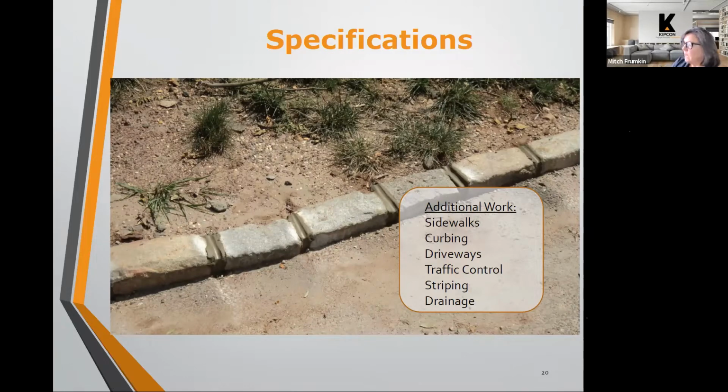The standard is that 24 hours after the end of a rainfall event, those surfaces should drain completely. That includes areas where there's slow running water. There may be some slow running water on the pavement, and 24 hours is the standard for that to clear off. If it's raining and you see water, that doesn't mean you have a drainage problem. You have to wait till the rain ends. After 24 hours, the pavement should be well drained. Maybe not dry at that point, but well drained.